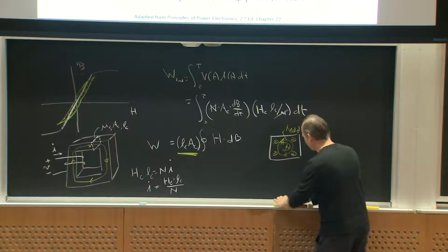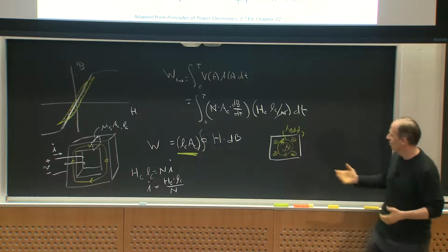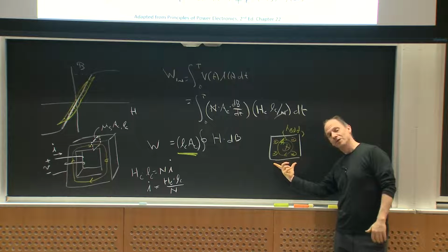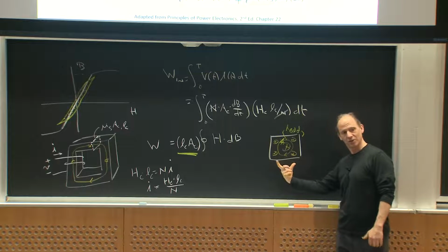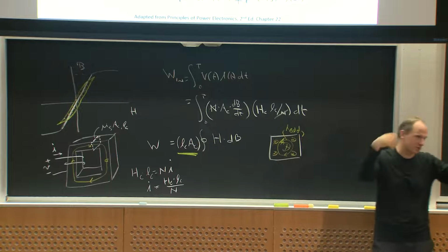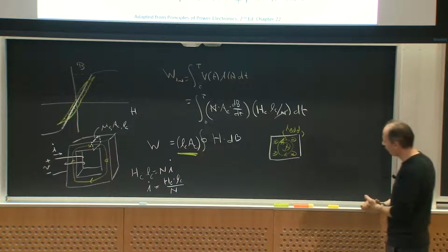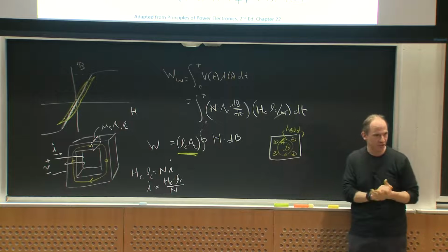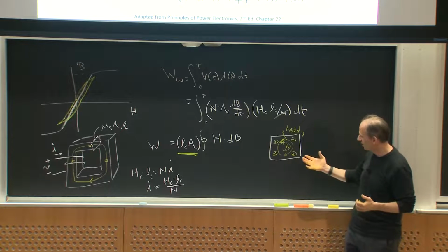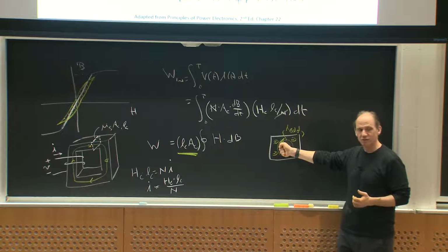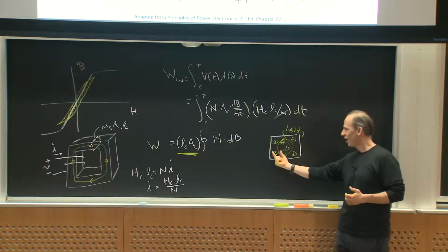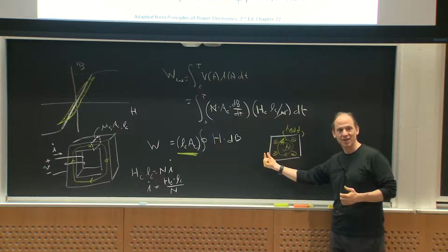When do I start to care about this eddy current loss? I care about it when the dimension of the core is on the order of the skin depth. Right? And if I get a core cross-section that's too big, two things happen. First, I get a lot of eddy current loss, and that just manifests itself as additional loss. And by the way, it scales up with area because I have more room for eddy currents to run around in. So it's not even loss per unit volume. It gets worse as the cross-sectional area gets bigger. But the other thing is, if it's bad enough, it tends to reject flux from the center of the core, and I might drive up the concentration of flux at the edges and might even saturate it.